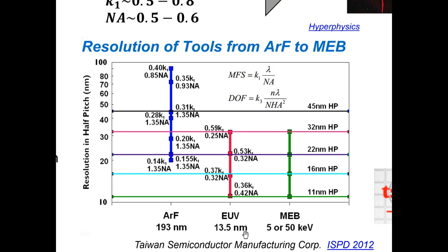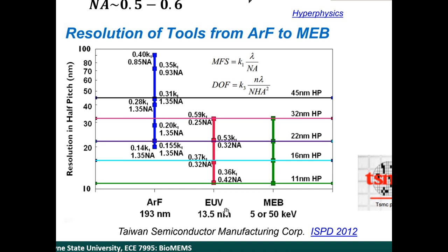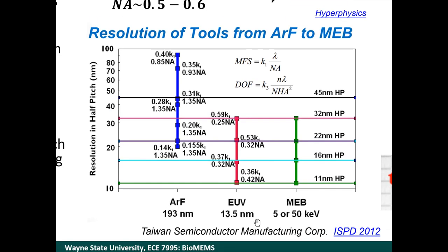And then an alternative technology, not a newer one, is to use electron beams instead of photons. When we're talking about light, we're talking about photons. This Rayleigh diffraction limit has to do with the wavelength of the photon or the electron. Turns out electrons can have a much smaller wavelength than photons can. So that's why electron beam lithography can get you down to even smaller sizes.